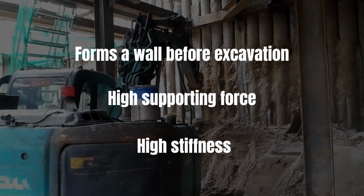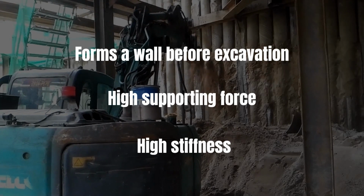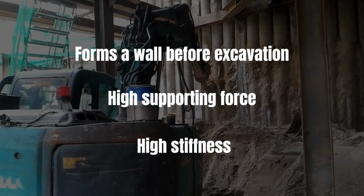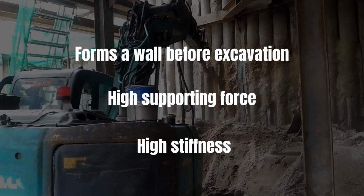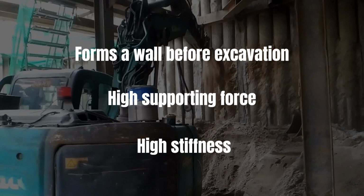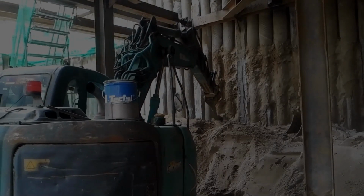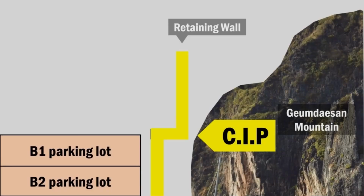The friction between these concrete piles and the surrounding ground increases, which increases the supporting force compared to other methods. Also, compared to the H-pile soil plate method, the wall stiffness is bigger, and it has the advantage of not being affected by the ground condition. These advantages are the reason why the CIP joint wall method was used for reinforcement. Moreover, we made the earth anchor of the existing retaining wall into two stages for additional support.